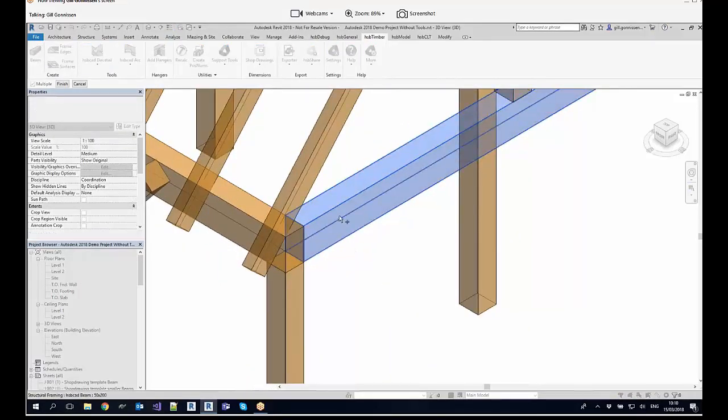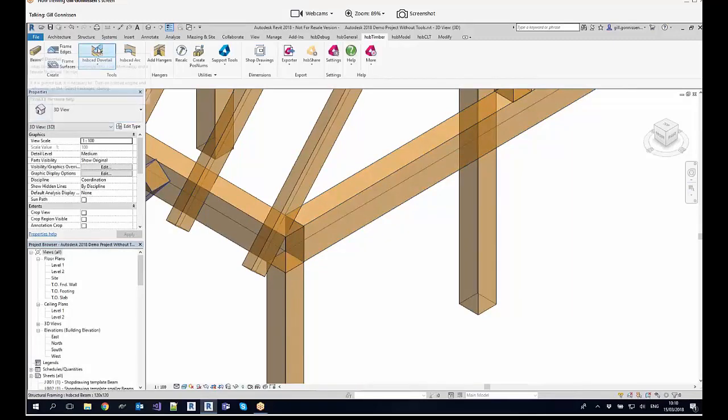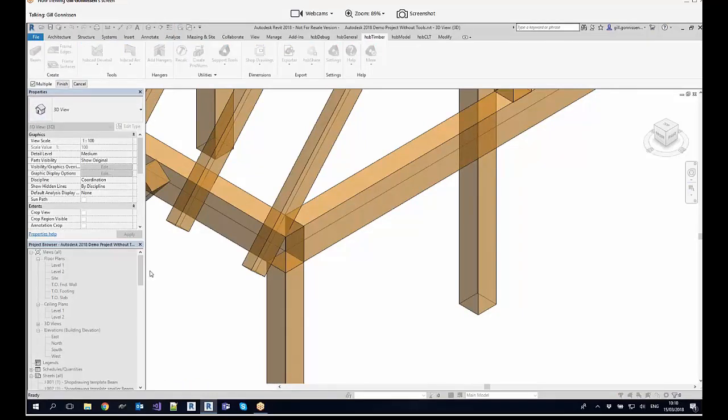As you can see, I'm going to start over just to notify what is going on. So I'm clicking on the Dovetail tool, and then Revit is giving me some information on how I should apply this tool. So on the bottom left corner, we can see the select male beams, and then we are just going to select the male beam.